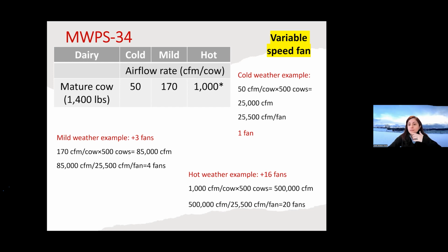So I think one option is to have variable speed fans. So a fan that we can tell, okay, it is cold now, you only work 60%. And then when it gets warmer, you can work 90%. We don't want fans to work 100%, because then it reduces their efficiency, but it's good to be able to have some control over the fan speed.